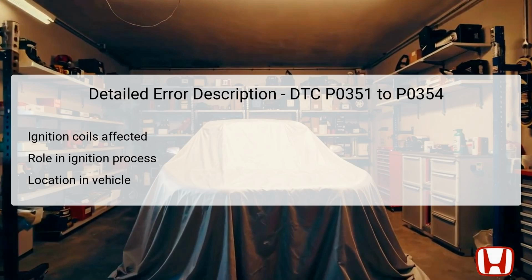P0351 for cylinder number 1, P0352 for number 2, P0353 for number 3, and P0354 for number 4. Any one of these malfunctions indicates an issue with the corresponding ignition coil circuit, whether due to a faulty coil itself, wiring issues, or problems with related components such as relays and the ECM. Correct identification of the faulty component is key to resolving the issue and restoring optimal engine performance.